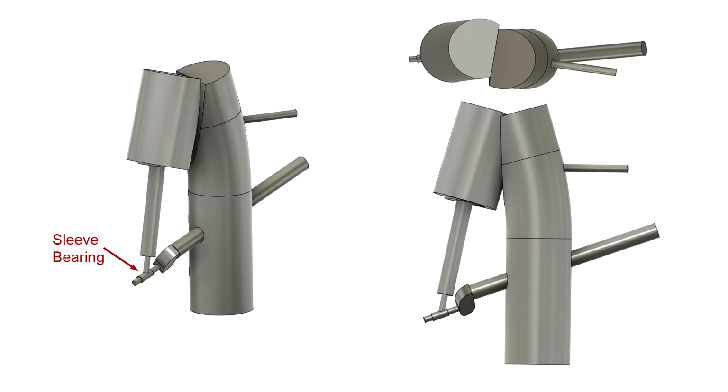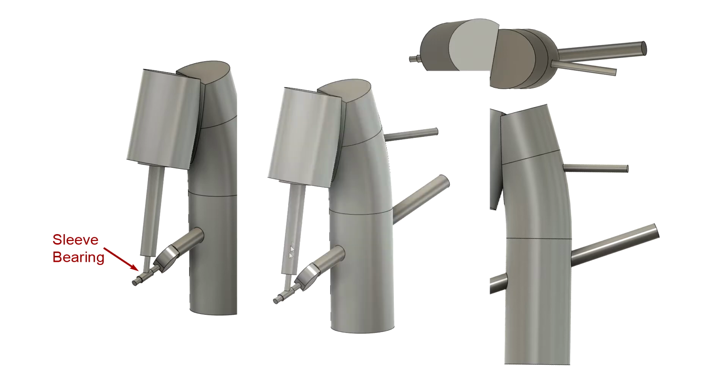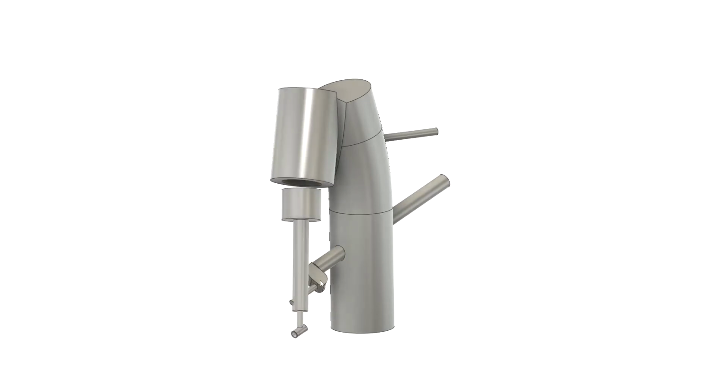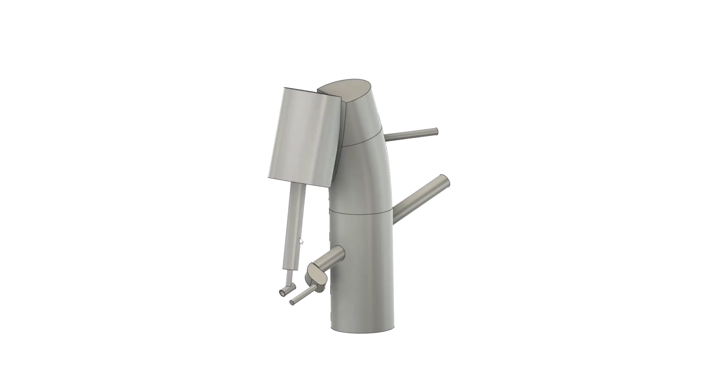Even though it seemed clear that it wouldn't work, the rod end bearing was initially constructed as a sleeve, mating with the skewed crank in one position. The model did assemble, but checking the CAD model behavior, the mechanism was frozen. The cursor won't move the mechanism. But suppressing the rod end joint, the remainder of the mechanism moves as expected, without closed-loop constraints. The rod end bearing seemed a good place to make changes.